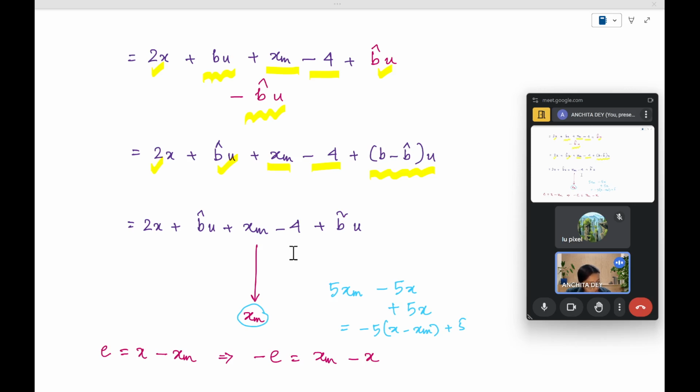And so then this would be minus 5b plus 5x, say plus some other terms based on however you design, right? So if your e dot is equal to minus 5b, that's good, because now your error would be converging exponentially to some bounded state based on whichever terms are there inside these dotted parts, right?